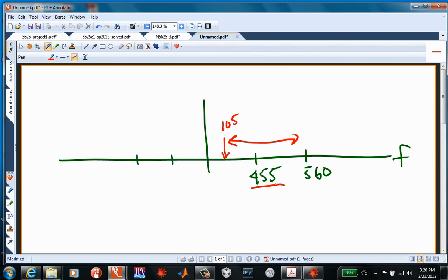It's actually going to be a signal that would add to 105 to produce 455. So that would be, let's see, got to do my math, 350. Okay, 350 plus a local oscillator at 105 would equal 455. Where'd you get the 350 from? Because I'm looking at my picture as opposed to working the equations, which to me makes more sense.